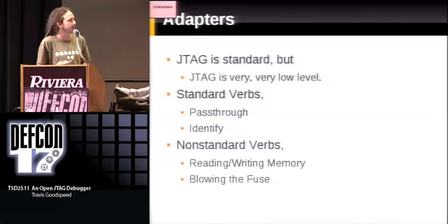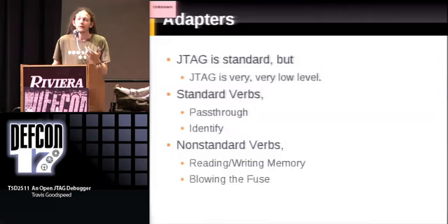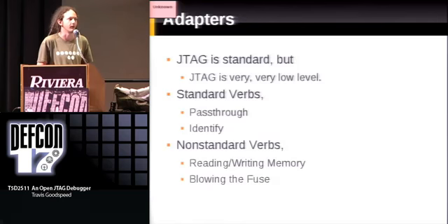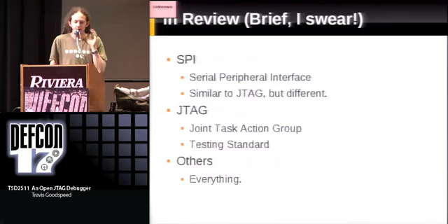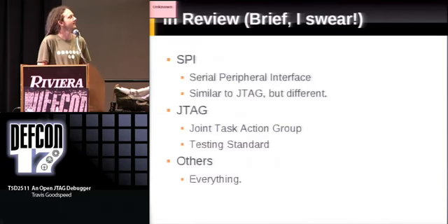In the case of the MSP430, no other verbs are supported that are in the standard set. So if you want to read or write memory, if you want to blow the JTAG fuse, especially if you want to write flash memory, you have to understand how the chip works, how it expects to be told what programming method to use. So to quickly review, and I swear that this will be brief, there's the serial peripheral